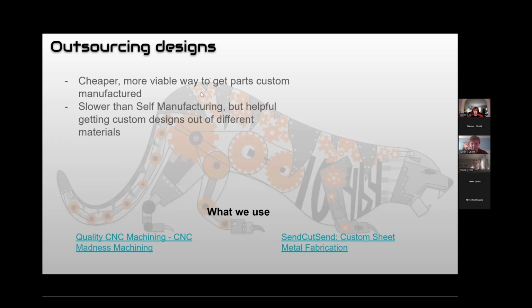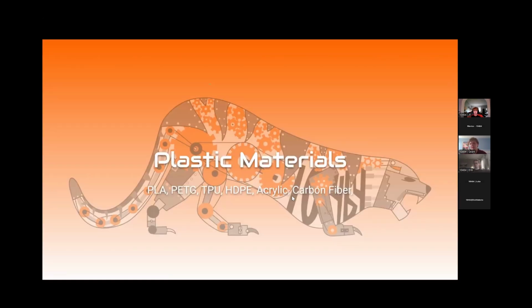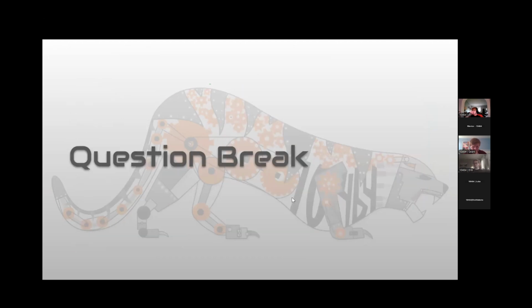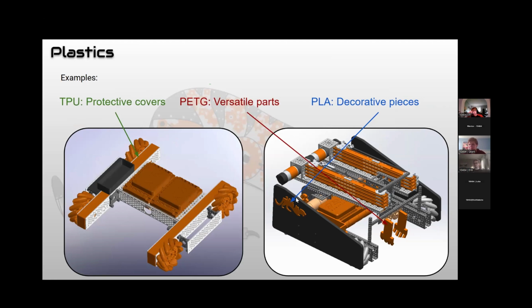Oh, for that, I'm going to go back to our picture, but I'll explain as we go. There's two ways we can do it. The way we're going to do it this year is to use some screw inserts for the plastic, and we're just going to melt them in with a soldering iron. The other way you can go, you can make solid cutout holes and put some standoffs in there, so you can screw into the standoffs, and then the plastic should be secure in place and won't be able to move because of those standoffs. But the way we're going to do it this year, because we want high strength and limited movement in the plastic, we're going to put in some screw inserts and melt them into the plastic.